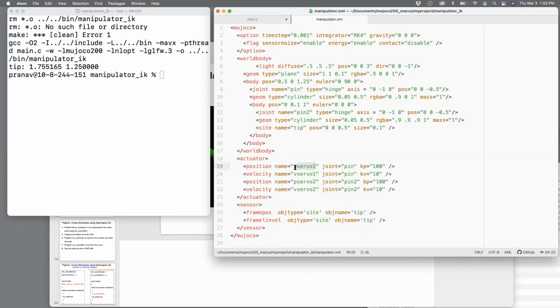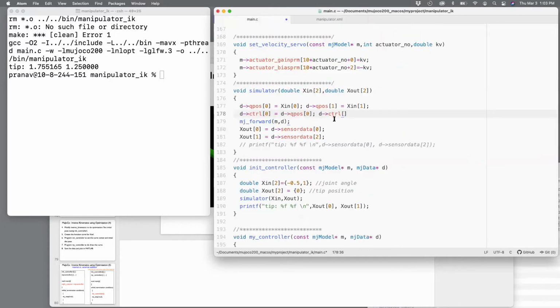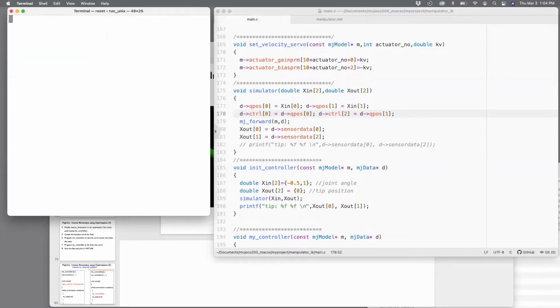The first one is the position command, so it'll be 0, and if you specify ctrl[1], that will be a velocity set point, which I don't want. I only want a position set point for link. That will be the number 0, 1, 2, so it'll be 2, ctrl[2] equals. So if everything looks right now, I think it'll work.